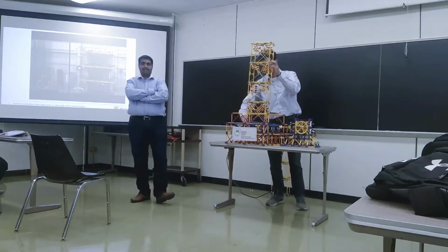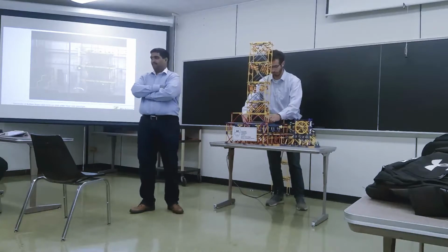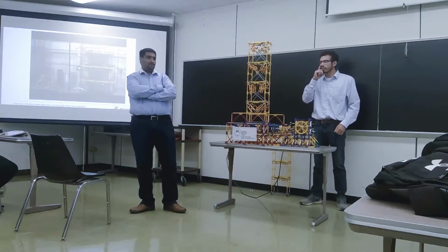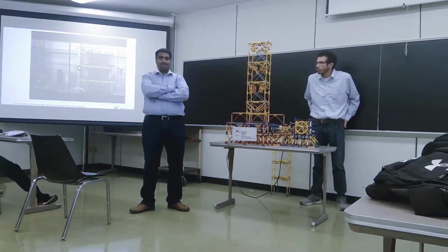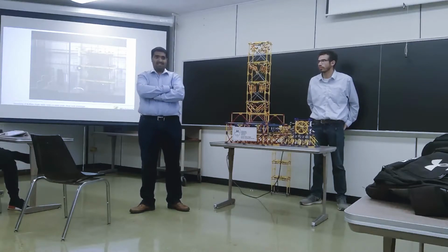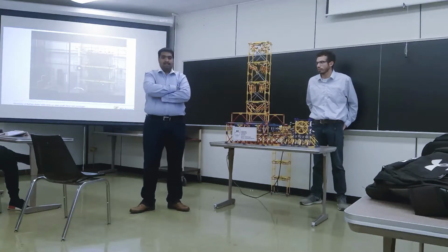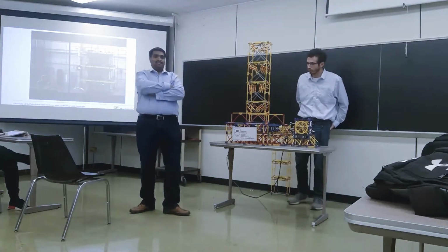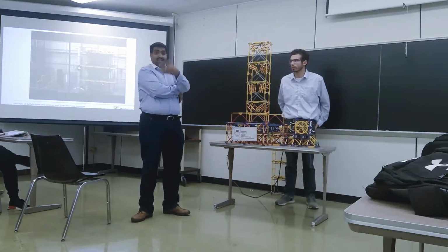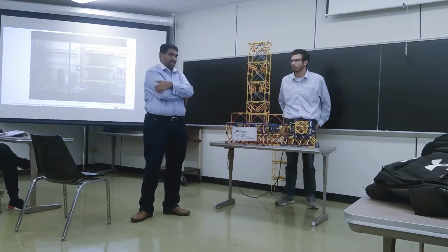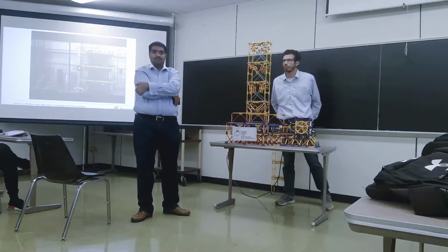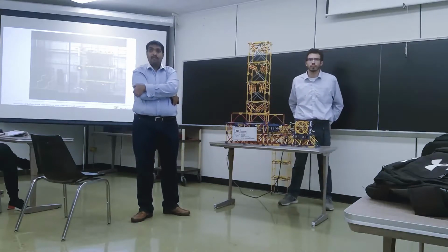So there is a whole research group called structural health monitoring or condition monitoring. Have you heard of that? Okay, so just like humans have health, structures also have health. We are trying to monitor the condition or the health of a structure, especially a building. So in this case, the idea is as buildings grow old, they don't have the same stiffness. They rust or they just decay over time, and the stiffness reduces. What happens when the stiffness reduces? Your frequencies are going to change, right? Change how?